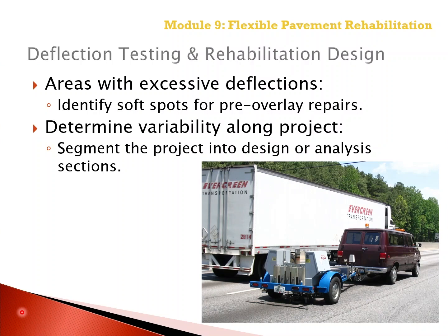Another very important activity or step is the deflection testing for rehabilitation design. Deflection testing provides a very good technique to identify areas with excessive deflections and/or to identify soft spots for pre-overlay repairs, especially if those soft spots are localized along the project.